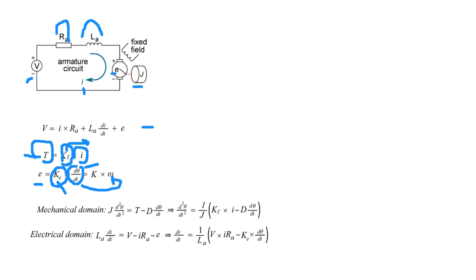So every motor catalog presents us the torque constant value. If you want to model, for example, last week some of you tried to model a DC motor, benefiting from the Michigan University MATLAB website. You remember you have a KT value, you have a KE value. It will be a recognized factor of your motor maximum speed value and maximum moment value. Generally, lots of companies present us their torque constant and their back EMF constant.